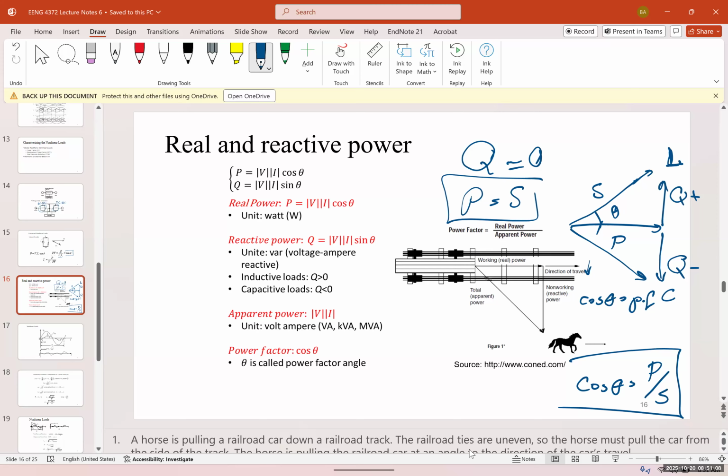What about a resistive load? For a resistive load, if we have a resistor, what is Q? 0. If you had measurement instrumentation, we solved it for average reactive power for a resistor. It's not storing any energy, so it's going to be 0. Q is 0, and in a resistor you only have real power, and the real power is equal to the apparent power. So for a resistor, P is equal to S, and Q is equal to 0.